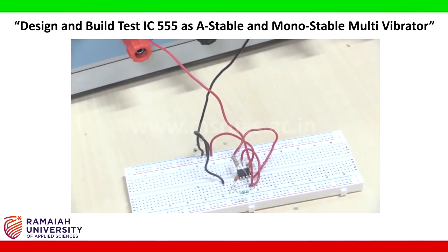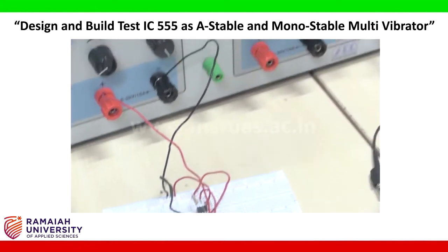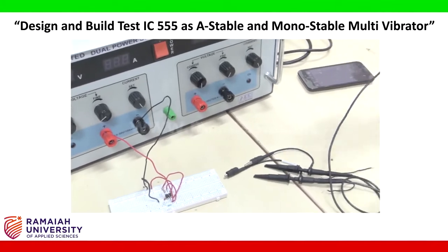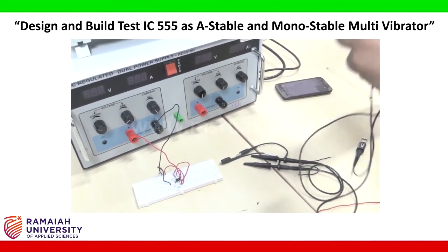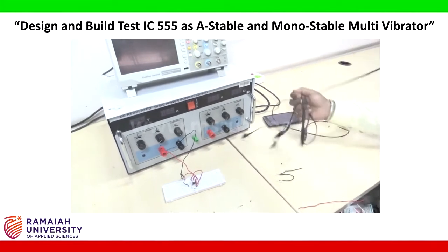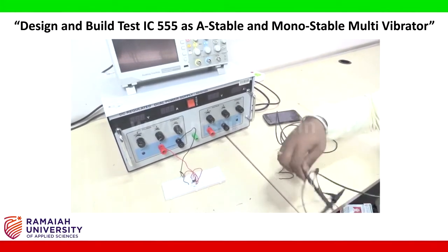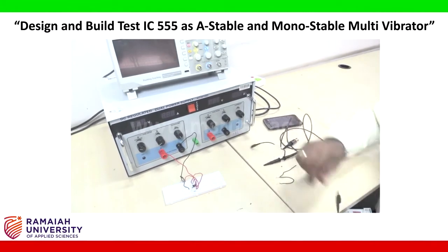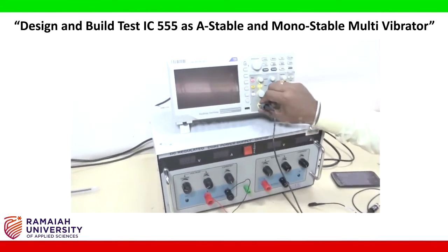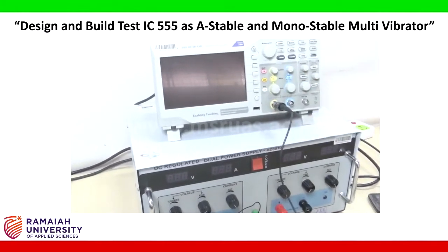Next I need to connect the output. To see the output, I am taking the patch card and connecting it to one of the terminals in the digital oscilloscope.